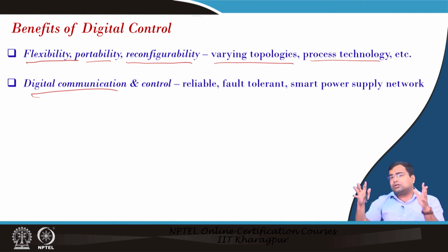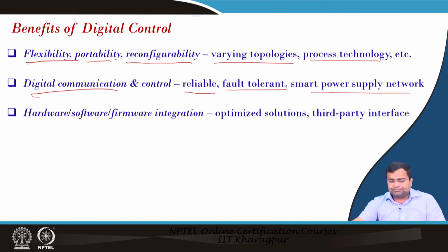So, you need to know the actual battery SOC status. That requires real time communication, and that is very much possible when your converter itself is working using digital control, because this inherently provides digital data communication. In this way you can make the design reliable, fault tolerant, and the power supply network can be smart.